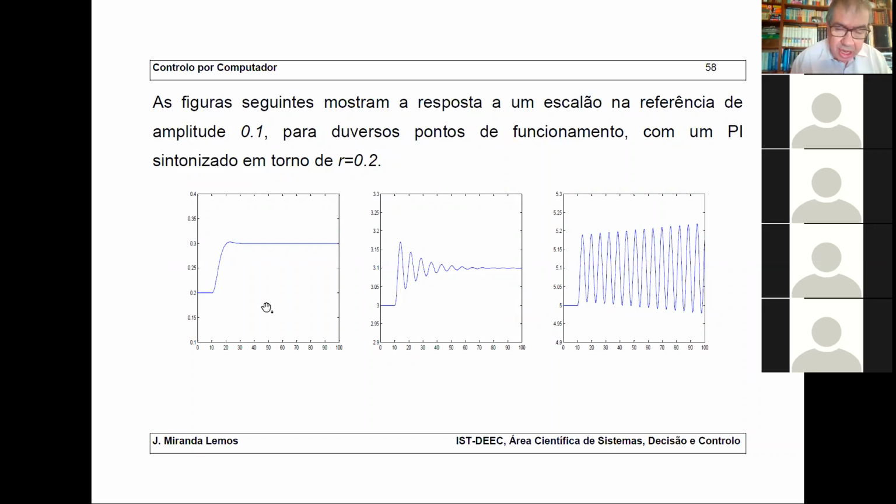So the table changes the gain of the controller. And if you move from 0.2 to 3, you are just going to reduce the gain. If you know the characteristic of the actuator, you can differentiate it, and you know the increase in gain, so you reduce the gain. Okay, so use a table.